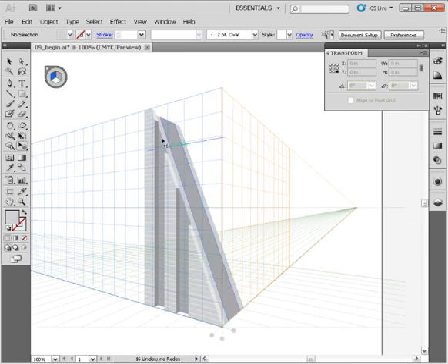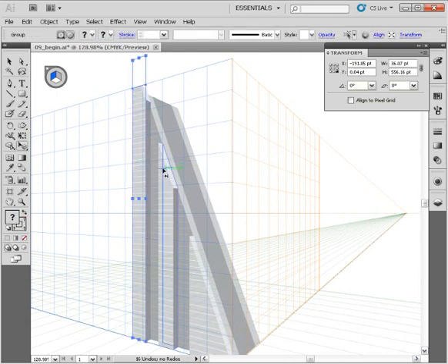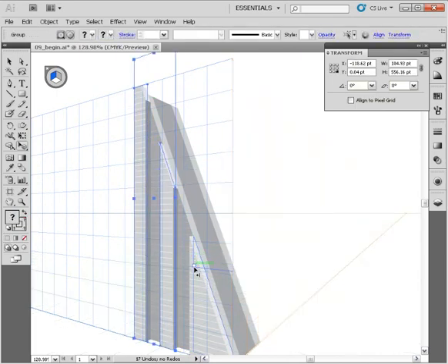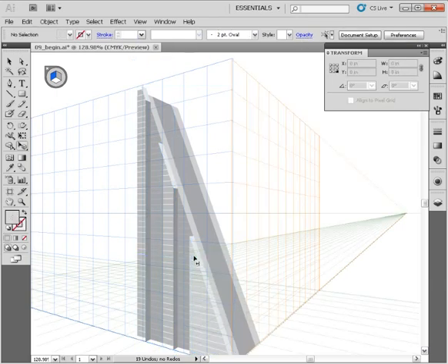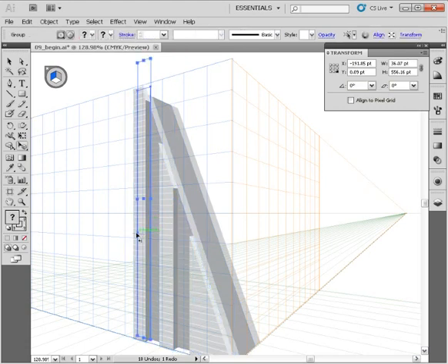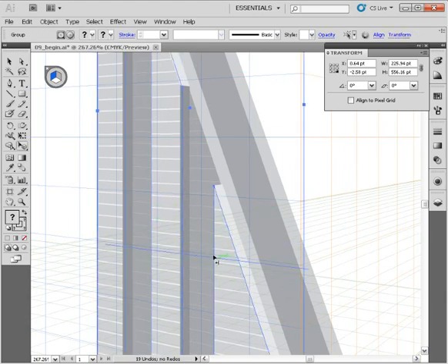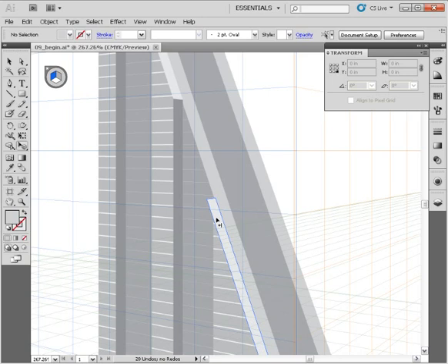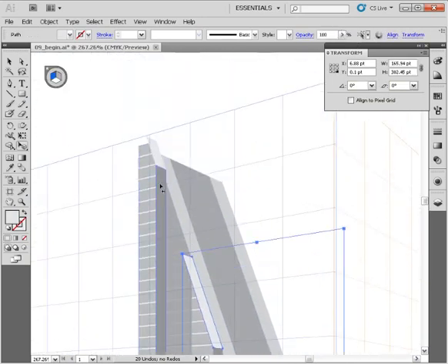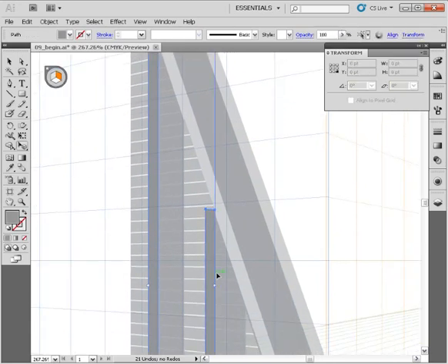Now at this point we're ready to start doing something similar with these protrusions for these column pieces. So we need to come in and hide a few of these pieces first. Let's hold down Shift and select a few of these faces that are closest to us on these protrusions. And let's hit Control 3 to hide those. Well, it looks like we had one selected here that we didn't actually intend to select. So let's zoom in a little bit closer. Make sure we have these frontmost faces selected. And let's select these top faces here, holding down Shift again. Hide those. And let's select these two inside faces as well and hide those.